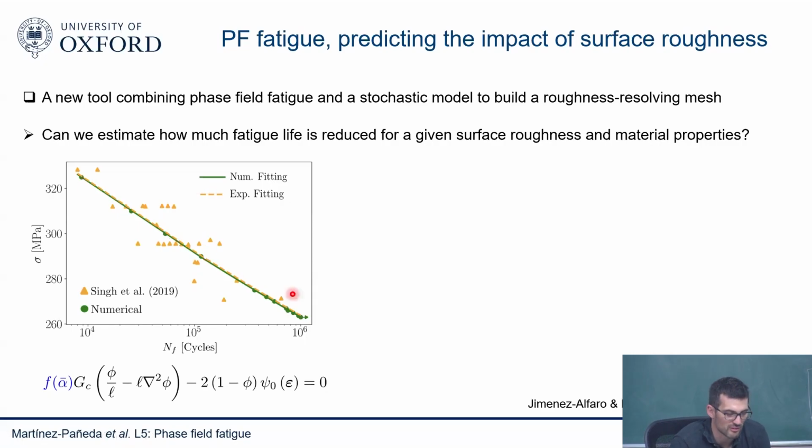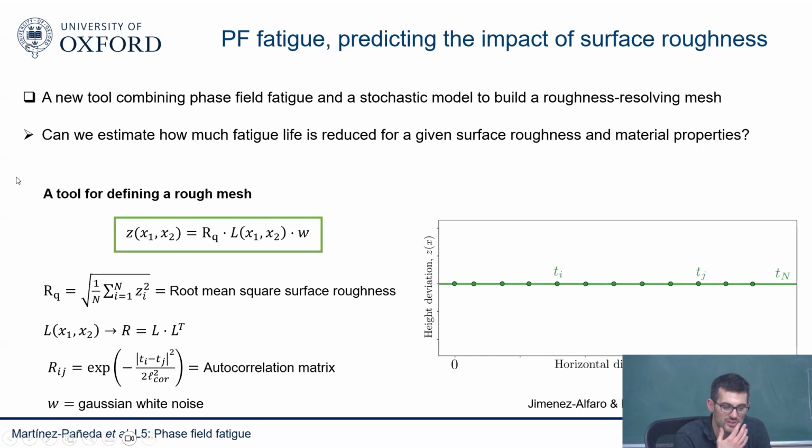So first of all, the fatigue model, we take the one of Ligesa, the one that I showed you before, and with this model, we seem to be able to fit quite nicely the experiments. This is on the smooth samples. The fatigue model seems to be working okay. Now the question is, what do you do with the roughness? You need some sort of a statistical model. So you need to develop a new finite element tool that allows you to capture this.